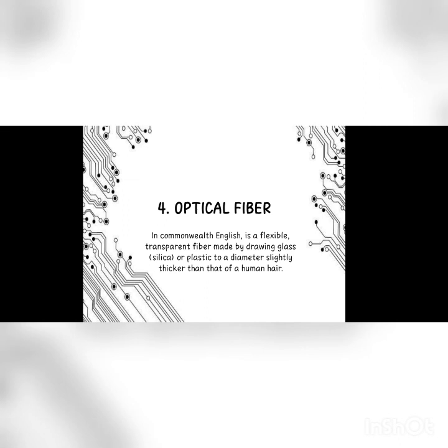Optical fiber. In Commonwealth English, it is a flexible, transparent fiber made by drawing glass, silica or plastic to a diameter slightly thicker than that of a human hair. An optical fiber is a cylindrical dielectric, non-conducting waveguide that transmits light along its axis through the process of total internal reflection.